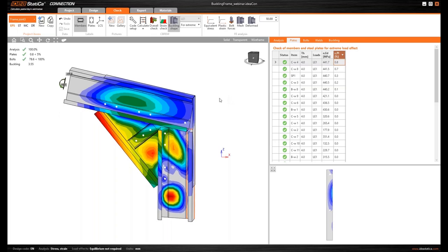The members for class 4 and slender plates cannot be used for plasticity that much. So this is definitely a good value. Maybe we can manage to push it down a little bit to 0.5. That will be even better.